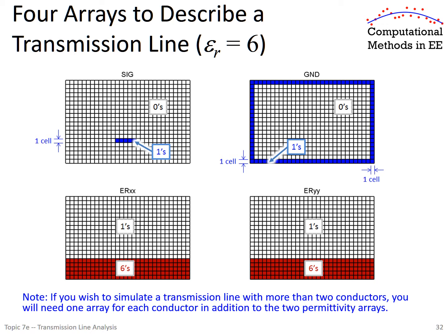Now, they will look very similar. They may just differ around where a boundary is. Now, this can get very confusing to do for curved geometries and how you sort all this out. And I have a very neat technique to show you that will make that very simple. But in the end, we're coming away with 2 more arrays describing the permittivity at each point, and they should look roughly the same. And in the case of the microstrip, they look exactly the same.